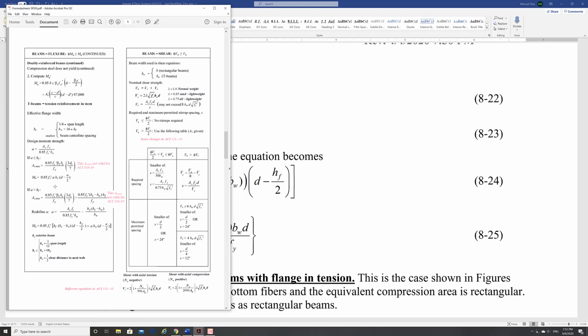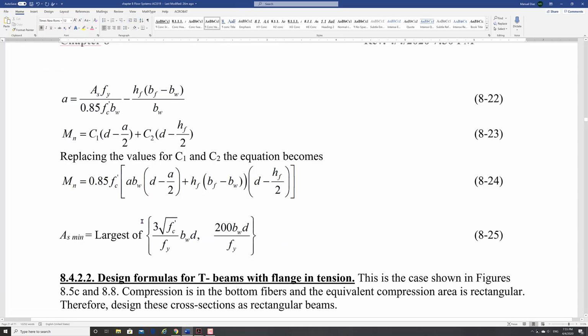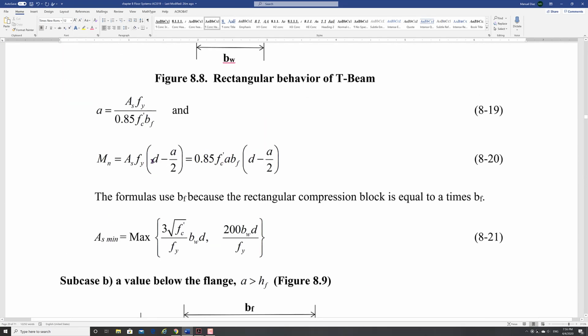The only difference is that the FE exam has decided to use the concrete force, which is your compression force, and we are using the tension value, which is the same. Right? This one should be pretty much the same, very similar. So here we use the tension side minus the effect of the flange, and here is the other effect again. But they tried to write the formula in terms of the concrete rather than the steel. The way we have it here is based on the steel.